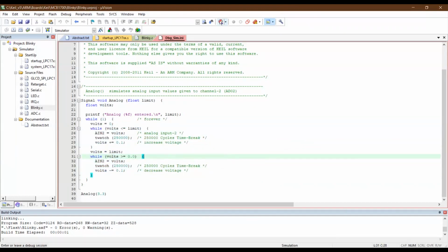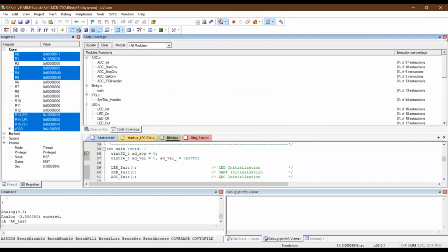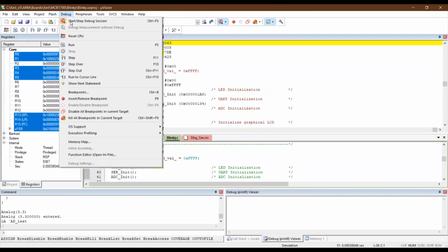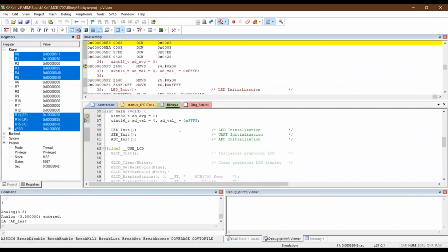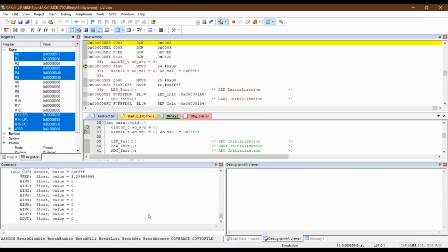So now we will enter the debugger simulation. You can access this from start and stop debug session in the debug menu. This program is a normal C program. Now to see what the virtual registers are, we use dir. As soon as I give V, it will only show VT registers. So this shows me all the virtual registers for the peripherals of this particular controller.